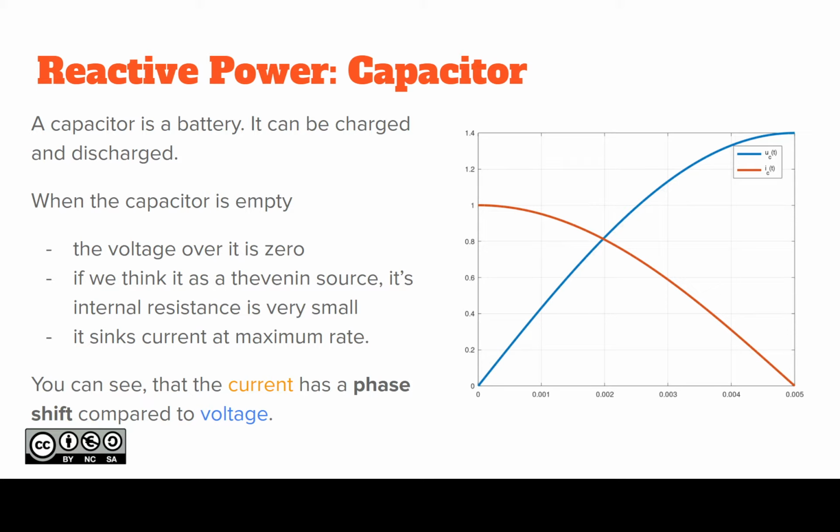So practically the capacitor at the beginning is empty, voltage is 0, but when you start with this quite rapid slope of the U, charging with the fast changing signal U, then the current jumps very high.